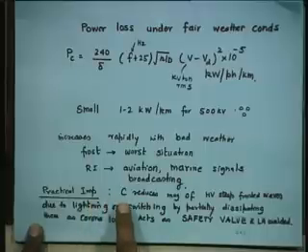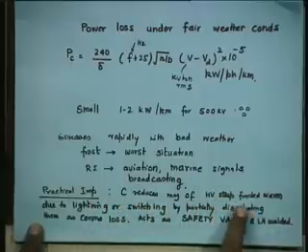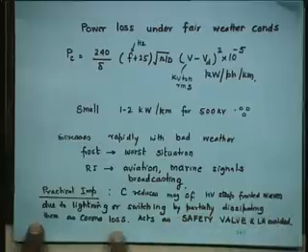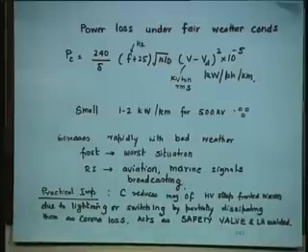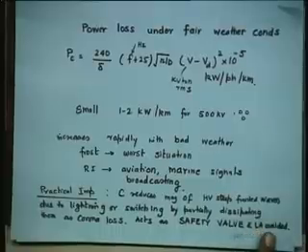So, the practical importance is that corona reduces the magnitude of high voltage steep fronted waves due to lightning or switching by partially dissipating them as corona loss. Thus, it acts as a safety valve, and you may not have any safety device like a lightning arrestor. LA is not Los Angeles, but lightning arrestor is avoided because of corona. So, it acts as a safety.